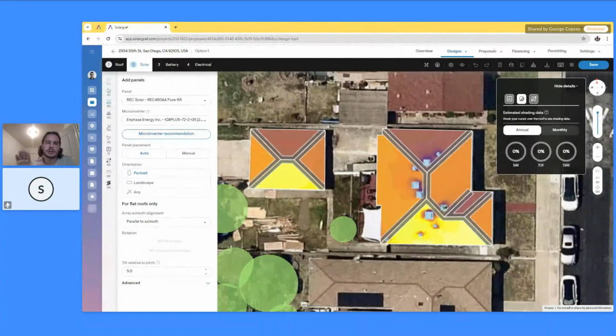The tilt, or the optimal tilt, I should say, is equal to the, I think it's the latitude, sorry, the distance away from the equator, essentially. And again, you can't change the pitch of the roof more often than not, but we will calculate how optimal that is, or how much that varies from the perfect conditions. So the tilt and the orientation relative to north or south is expressed here as a percentage.